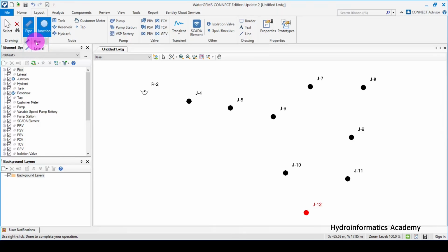If I click this, you can see now we have something at our cursor. If I want to take water from this reservoir to these areas here, I'll just click this once and again this once. As you can see, we have our pipe just like that, and also this one. From here I need to move to this area.